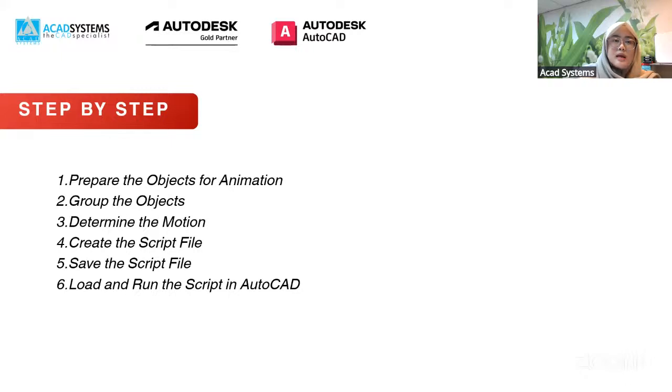So this is step by step. The first one, you have to prepare the object for animation. The second one, you will group the objects. Third one, determine the motion. And then you create the script file and save the script file. The last one, you will load and run the script in AutoCAD.